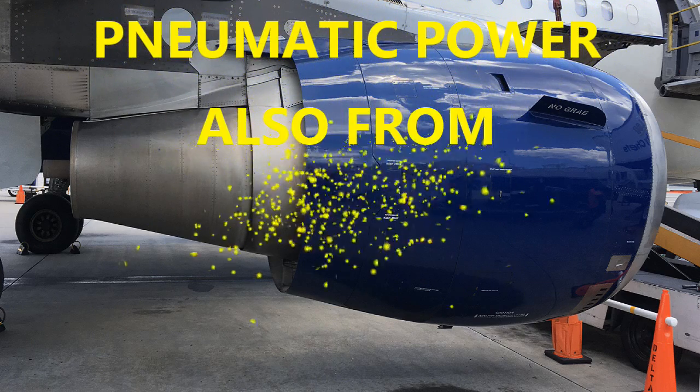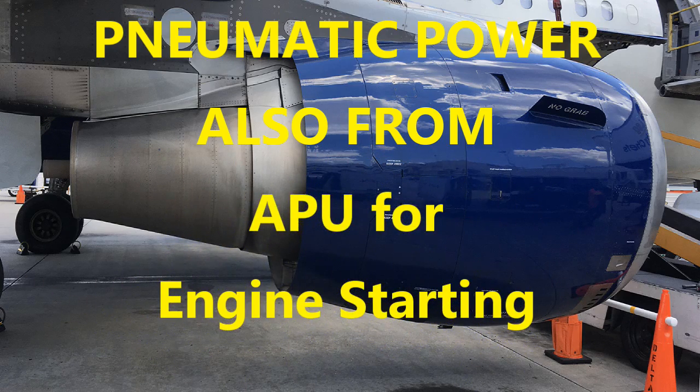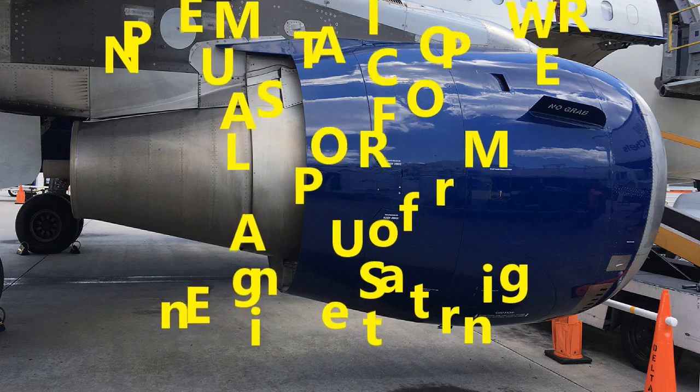I mentioned the sources of bleed air, coming not only from both engines but also from the APU load compressor module. If you remember from some of the other GEM FAMs you might have taken, there were limits to the supplying of air from the APU at certain altitudes, and it depended on whether it was providing enough air to supply electrical power along with helping with hydraulics.